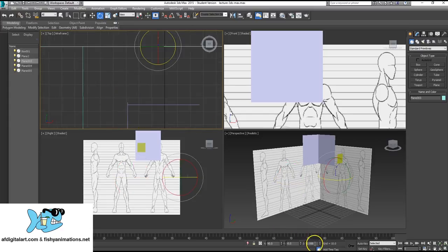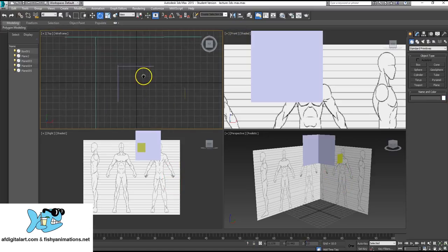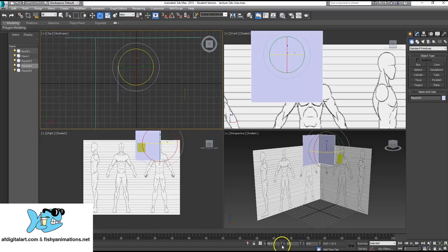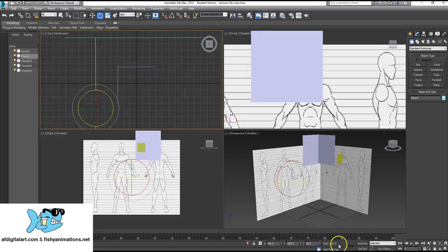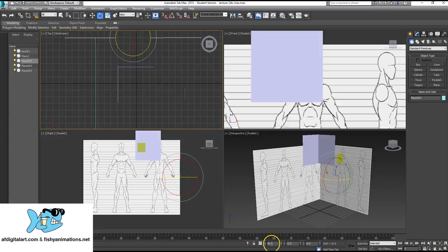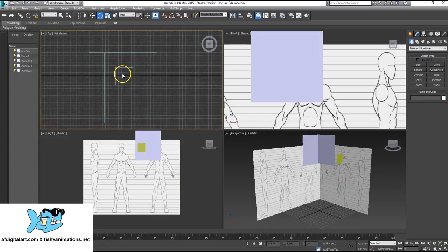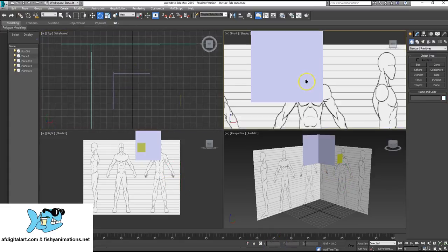And then these down here are actually 0. There we go. So that way they're not a little crooked. You can use those X, Y, and Z positional values and make sure you're doing 90s on these. Whoops. You can see I moved this one. This is actually supposed to be 90, 90. Perfect. 90, -180, 90. Sometimes you're going to see -180. Whatever the negatives, make sure that it's not a weird number like 89 point something. You're a little bit off, okay? And that way you've got perfect planes to work with here.